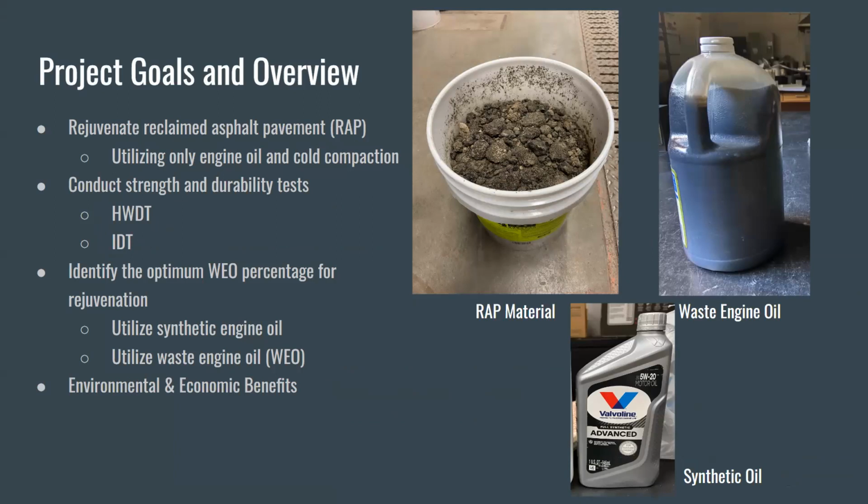Tests were first performed with virgin engine oil, and after the optimum percentage was determined, we applied it with the waste engine oil, ran the same test, and assessed the results. Additionally, this project yields an innovative pavement base that is environmentally and economically friendly. Being that these materials are disposed of in a landfill post-consumer consumption, this project benefits the environment by extending the useful life of both materials and eliminates the costs assumed with virgin material procurement.